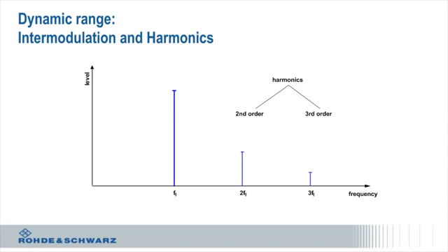So when you're looking at the dynamic range of a receiver, this is really everything coming together. I'm saying I want to know what's the smallest signal I can receive. This, again, could be my cell phone. What's the smallest signal I can receive? I'm far away from the base station, and I can't really hear it very well, so it's a very small signal. I'm worried about the noise figure of my front end, to a very big signal where I'm close to the base station, and it's really big, and I'm going to get these intermod terms or perhaps even harmonic terms. So when you design a system, you're looking at the dynamic range, i.e. the very smallest signal all the way to the biggest signal.